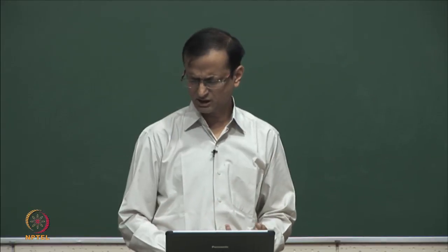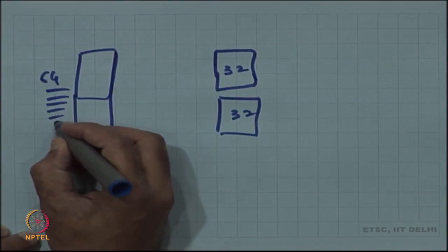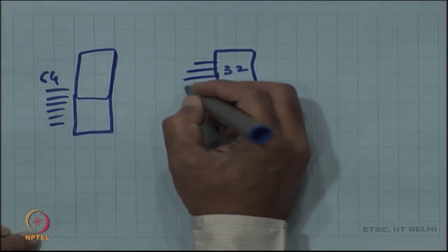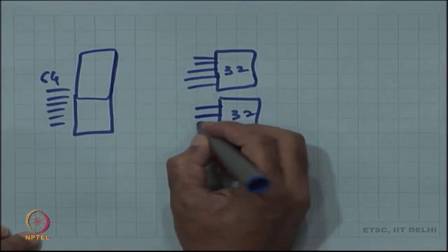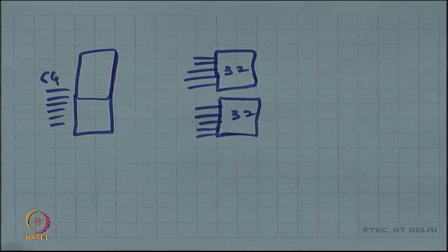But in addition, I can do just a little bit. So, there are 6 inputs here. Now, this one takes 5, this one takes 5. What else? The sixth one is deciding if it is this one or this one. The selection line to a mux can be that.